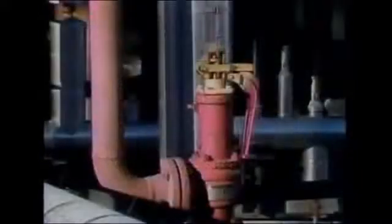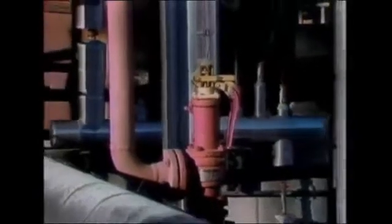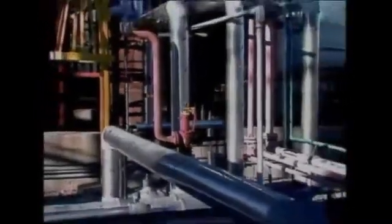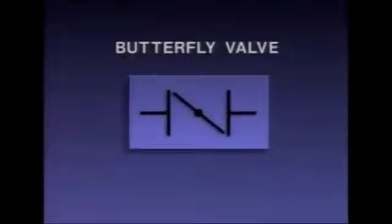For example, many systems use safety valves to relieve pressure. Safety valves are designed to pop open when system pressure exceeds a preset limit and stay open until system pressure drops below the pressure at which the valve is set to open. This is a common symbol used for a safety valve. You may also see it represented this way. Another common type of valve used in process systems is a butterfly valve. Here is the symbol for a butterfly valve.